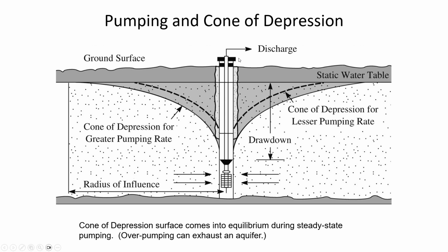If you had a well that you'd turned off, after a couple of days, the water level would just rise to a certain elevation that's reflective of the aquifer in general. But in the proximity of the well, if you turn on pumping, it's going to draw down the water level near the well because the water that's getting pumped out has to be replaced.